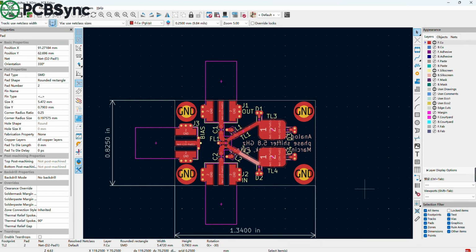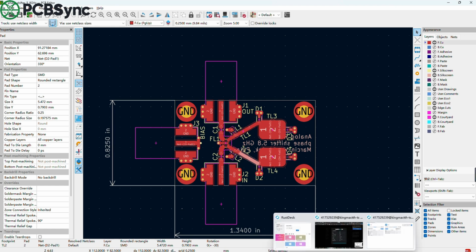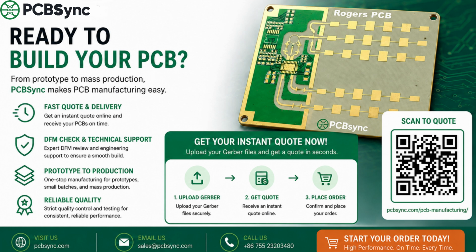Let's look at this again in the context of a circuit. Suppose the same 5.8 GHz RF design needs to use both RO4003C and RO4350B. At least 3 items need to be rechecked. First, recalculate the impedance for the corresponding trace width. Second, recalculate the physical length of the transmission line based on the dielectric constant, Dk. And third, combine the copper foil surface treatment and the processing factory to reevaluate insertion loss and phase error. Selecting high-frequency materials isn't just about comparing a single Df value. You need to truly consider the actual electrical performance requirements. You have to put all the conditions together to make a judgment.